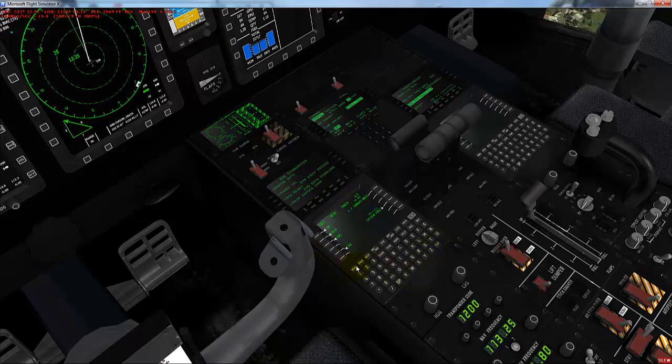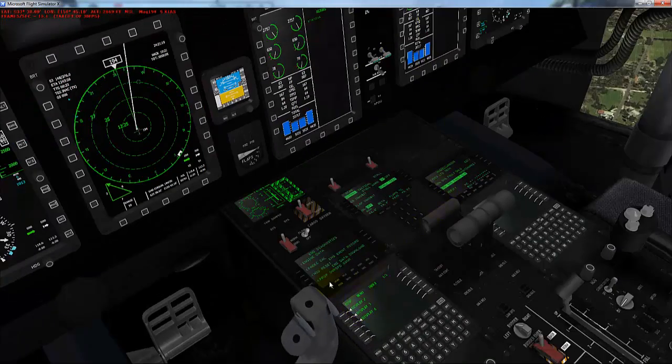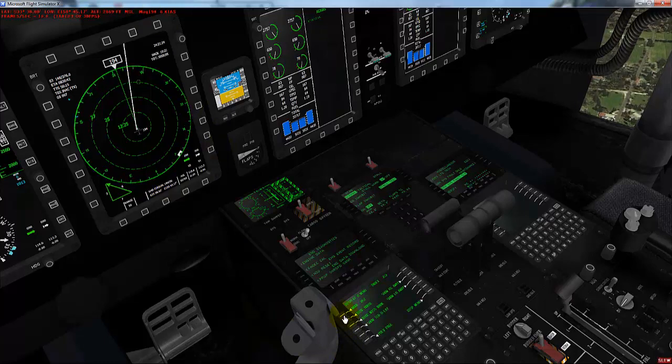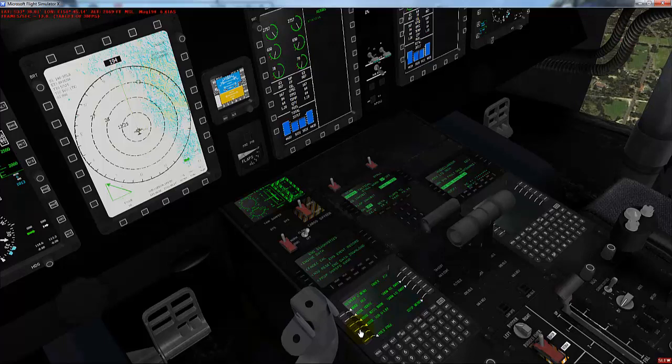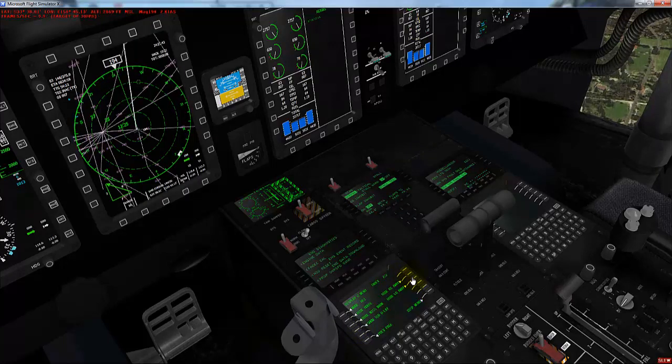Moving to the menu, you'll notice we have display. This allows us to change the active display features on the MFDs. Do not use the buttons along the side anymore. So we can change from HSI, which is currently active on this screen, and here we can hide our route or show our route. We can show or hide the mission marker. We can show the terrain overlay, or we can hide it. We can show our high and our low.